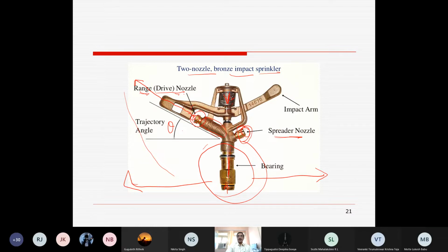So from there, if you recall, we have learned that discharge from an orifice is equal to C A root 2gH. In orifice water conveyance as well as in measurement, we have learned about discharge coming from an orifice, meaning water is stored in a tank and you have just a small opening. So it is called an orifice in a water supply system, and you have learned about the orifice plate as well in pipe flow systems, which has a smaller opening than the pipe size. So there we can find out what the discharge is.